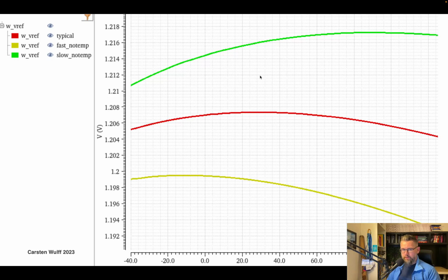Now, of course, when you simulate corners and look into corners, it's going to change, because properties of the diode voltage, or VBE voltage, might change. It might be the doping, it might be lots of things. The diffusion constant for electrons, it might be the lifetime of electrons, it might be the intrinsic carrier concentration, potentially. And I would encourage you to actually look into the equations, dive a bit deeper on the diode voltage, because you start to then realize that multiple factors matter.